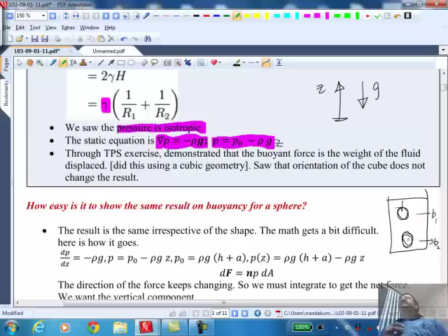The weight of the fluid that is displaced is the same at both locations, so the buoyancy force must be the same. Its weight hasn't changed in going from one level to the other level, so it should be at rest. So a neutrally buoyant particle will remain at rest wherever you position it. The fact that the pressure at 2 is higher than the pressure at 1 doesn't change the buoyancy force. But it is true that the pressure at 2 is higher than the pressure at 1. Right?